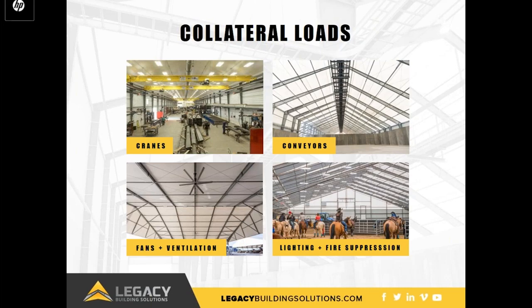Supporting collateral loads is one area where rigid frame fabric buildings have a clear advantage over buildings using open web trusses. Trusses are fabricated in standard sizes, leaving customers to choose between an under-engineered truss or a more expensive over-engineered truss. Because trusses are more prone to movement under environmental loading such as wind or snow than rigid frame designs, this often leads to increased maintenance and downtime on systems with moving parts such as conveyors or overhead cranes as compared to similar systems hung from the rigid frame system.